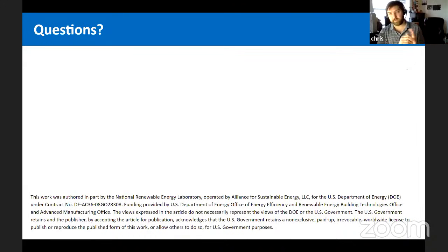And there are options with Dragonfly if you don't want to count the surrounding buildings, because a lot of the calculation time of EnergyPlus accounts for that. There are ways to turn it off, but by default, you're going to get the surrounding buildings in each model of the exported OSMs and IDFs as context shade, and so you will be accounting for that.